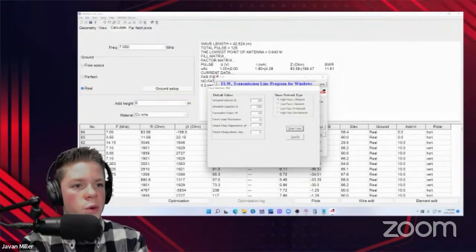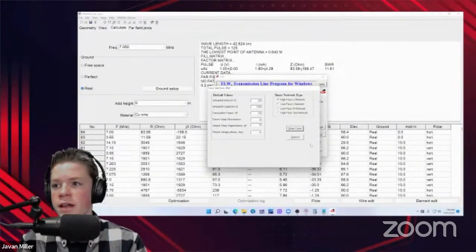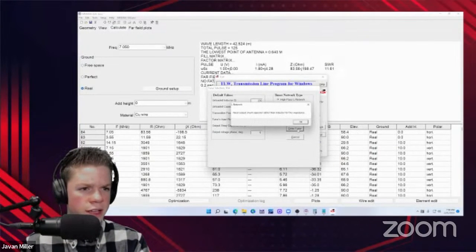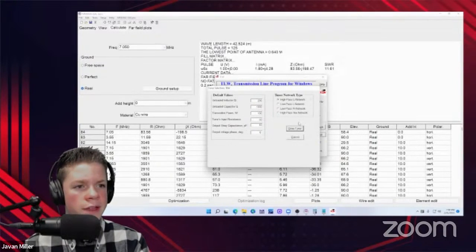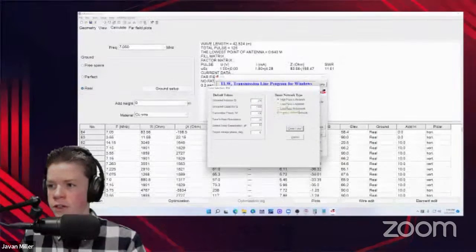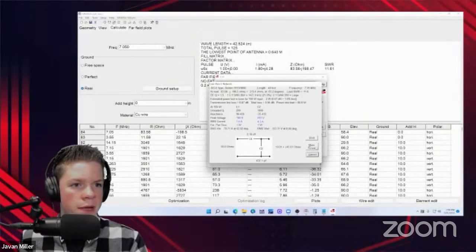Okay, so the tuner itself cannot match this solution. You either can do this as a shunt, you need a shunt capacitor for the output, or I guess we could try the other L network configuration. That should be able to match it.